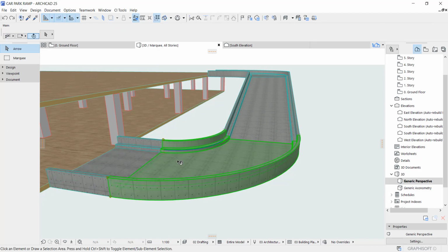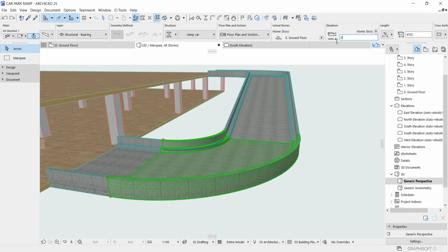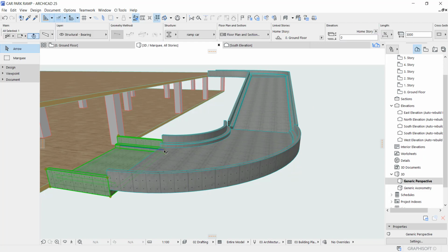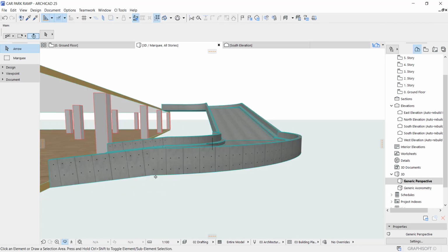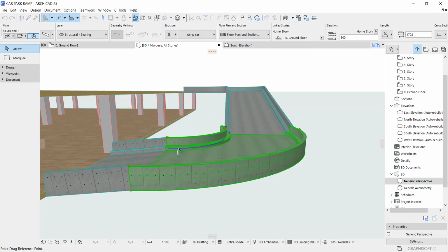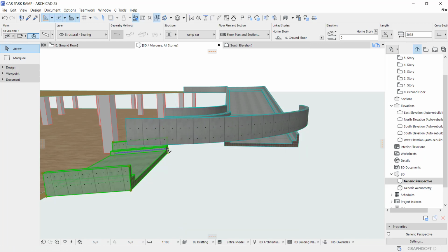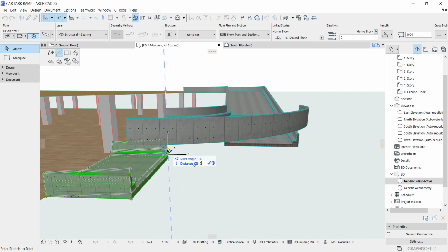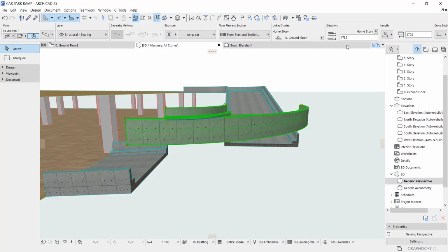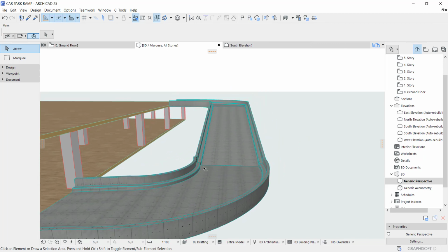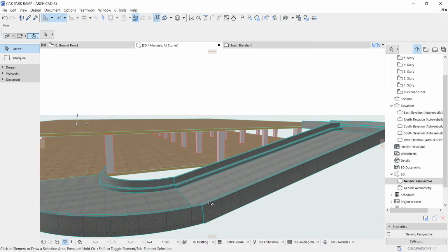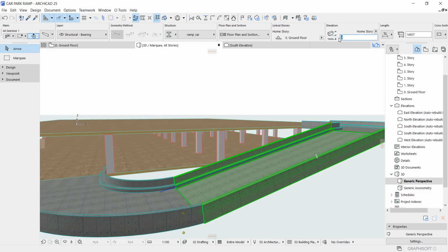It's giving us something else. In fact, let's elevate this by 300 so we can connect it to that top. Okay, I think this steps a little bit. Let me just take this up for a moment because it affects this. Take it up by 200. This one, make it 200. So with beam, we can't change the transition of this particular one here, from the look of things. So this one starts from 200 also.